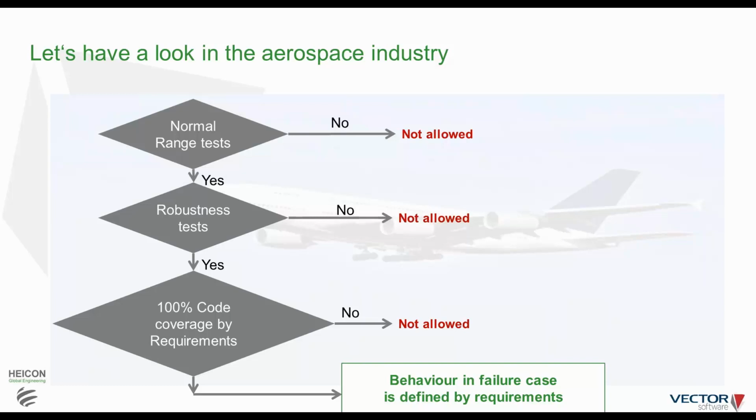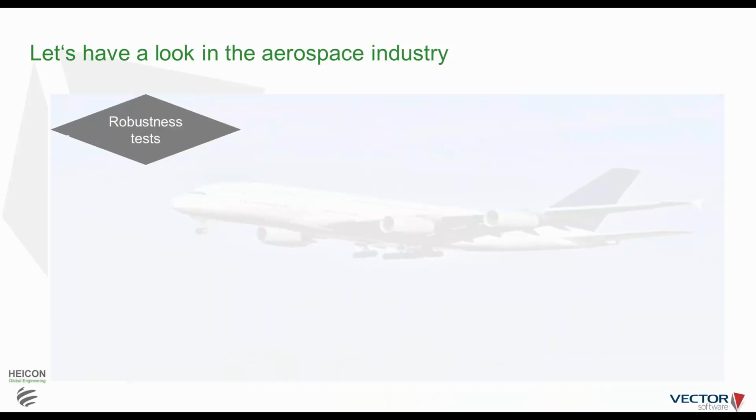You have an expected behavior defined, yeah. 60 kilometers an hour, system shall switch off. There's nothing undefined, it's clearly defined. And that's the big, strong advantage, and therefore there is no need to define other test methods. Actually, there is requirements-based testing with normal and robustness testing, where you test the edges of the requirements and above, and re-question the requirements. If you do so, then everything is covered.